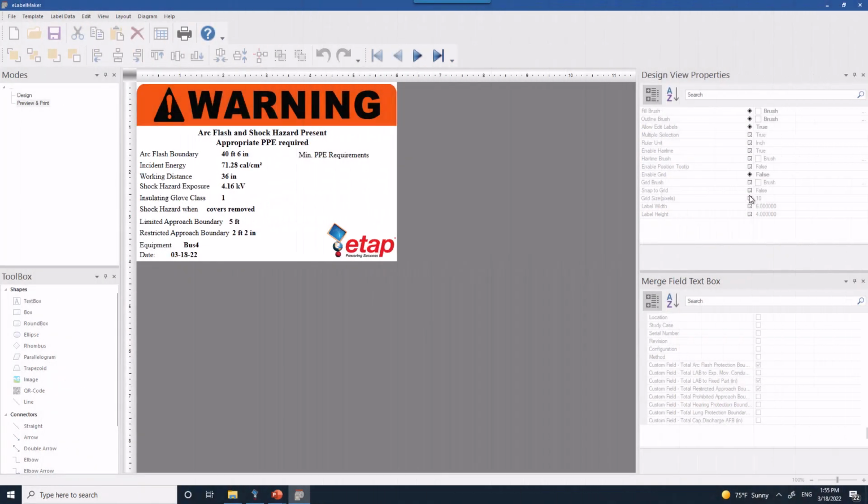The next big challenge that we have when we prepare arc flash labels is formatting. The arc flash analyzer from ETAP provides values based on the report database and the corresponding regional settings. If it's in English, you get it in feet and inches. If it's in metric, you get it in centimeters and meters. However, the presentation of a particular arc flash incident energy or arc flash boundary in a label is subject to change depending upon the value calculated by ETAP and the corresponding way it is presented in the label.